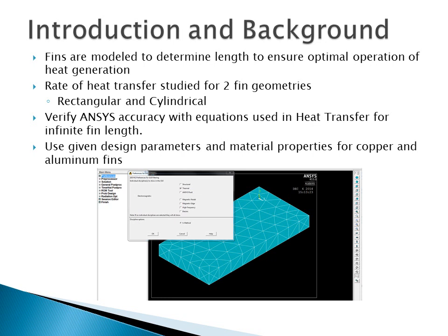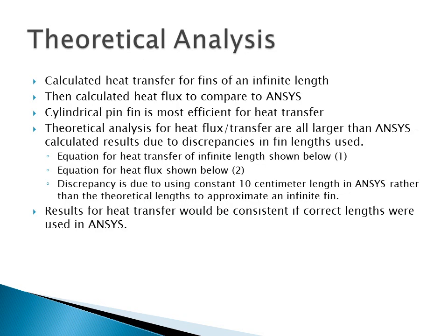We verified the ANSYS accuracy with equations used in heat transfer for infinite fin length, and we utilized the design parameters and material properties for copper and aluminum fins. So we calculated the heat transfer for fins of an infinite length and then calculated the heat flux in order to compare it to our ANSYS results. The cylindrical pin fin was the most efficient for heat transfer in both cases.